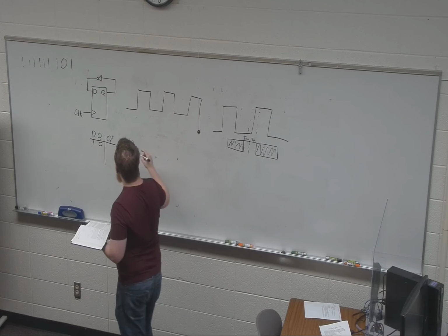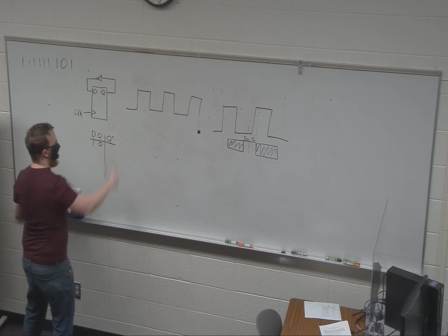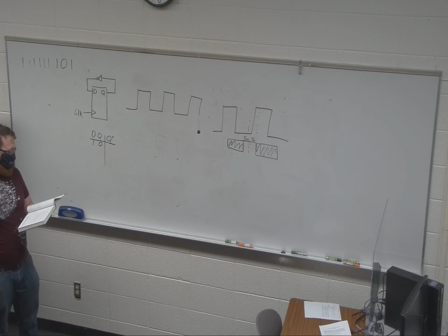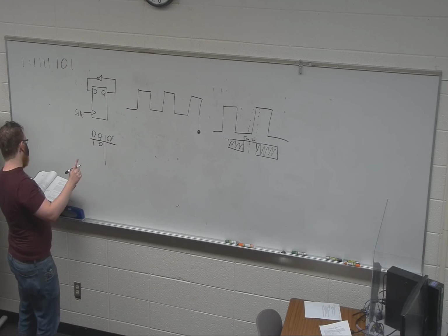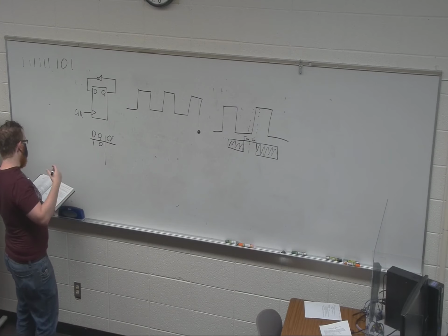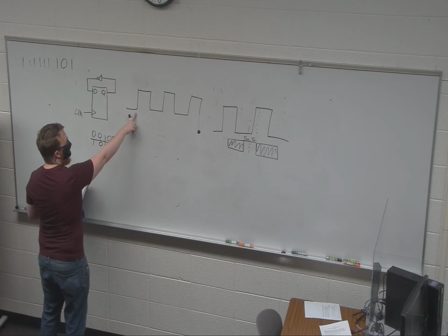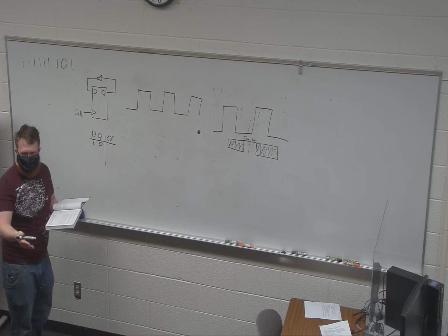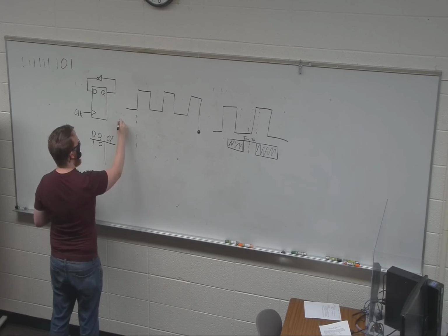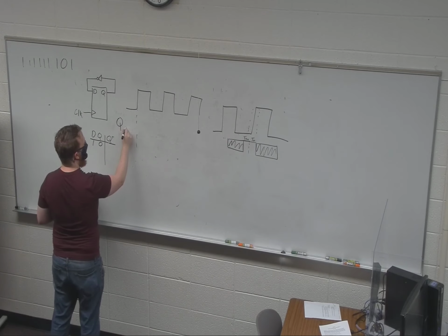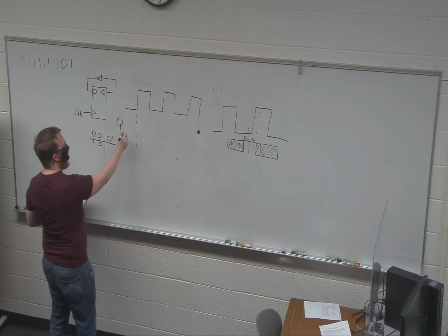So this clock is ticking along. We're going to say this is rising edge triggered, right? And so Q is going to want to pull in from what D is. So the clock happens. There's some delay in the flip-flop. So here's the clock. Here's Q. And Q is 0.